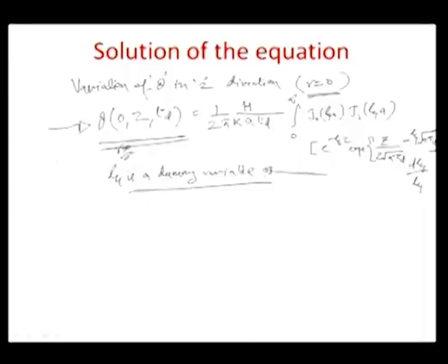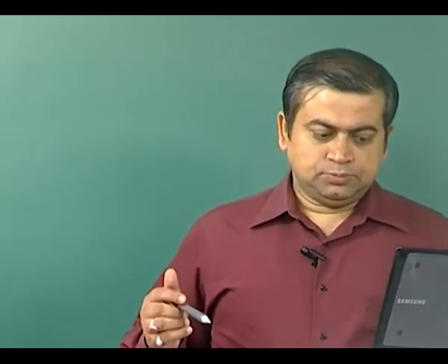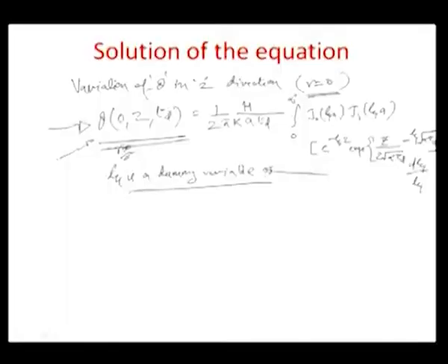So, with this combined parameter method, you can get this estimate at the center of the spark at r equal to 0, corresponding to all z's and all the depths which are obtained, and all the time of discharge which is treated to be constant by our assumption in this particular case for the spark. So, having said that, we now have a relationship between the temperature and the depth in the melting zone.